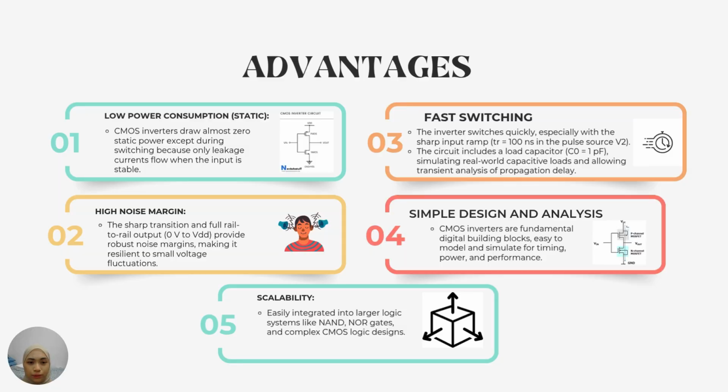Okay, hello, my name is Iman Akhtar binti Dasmim. So today I would like to present my part, which is advantages and conclusion. So the advantages is low power consumption, static. CMOS inverters draw almost zero static power except during switching because only leakage current flows when the input is stable.